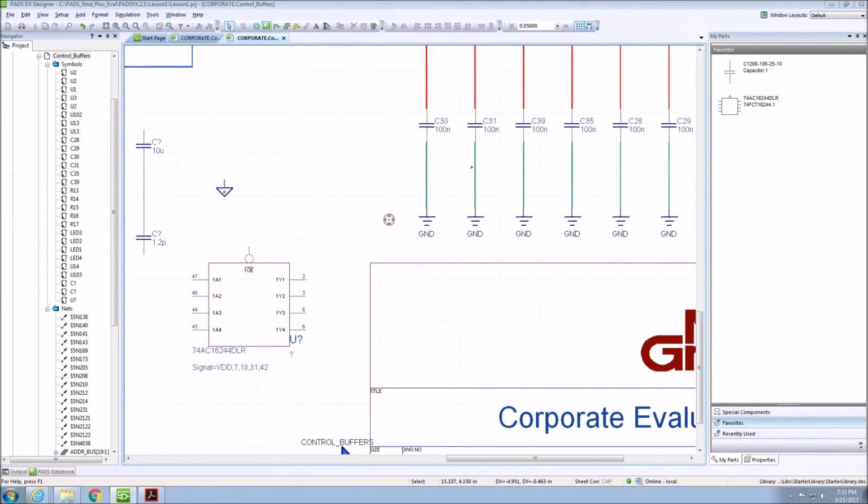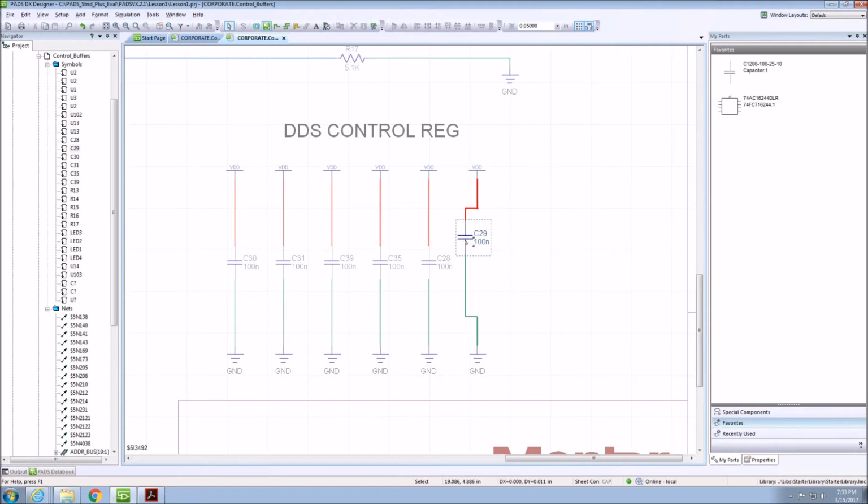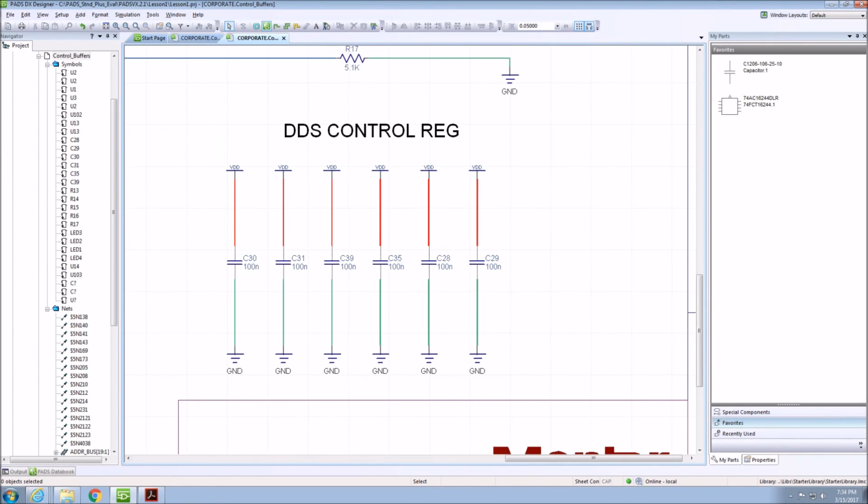In order to ensure your components are aligned the first time you place them, enable dynamic alignment markers. This allows like components to have a dotted symbol when they are aligned with other components. Also, if they're dragged in the correct spacing, they will have arrows indicating this.